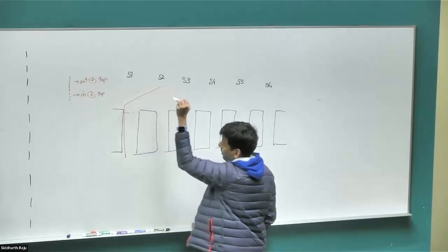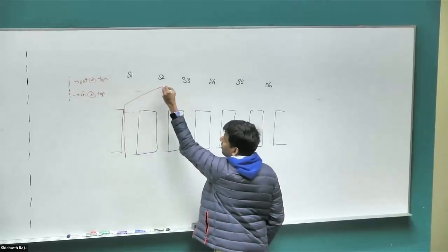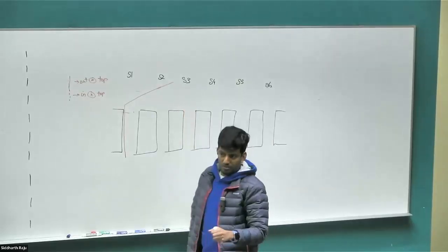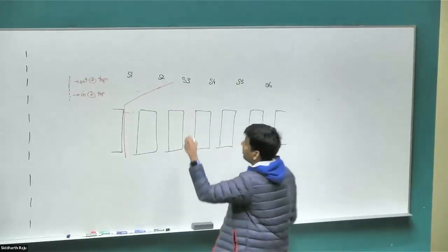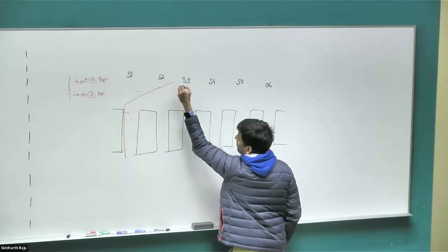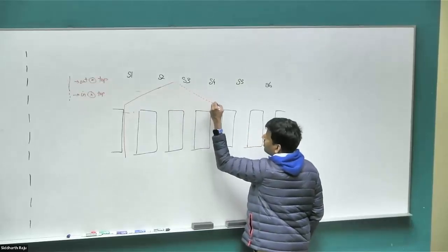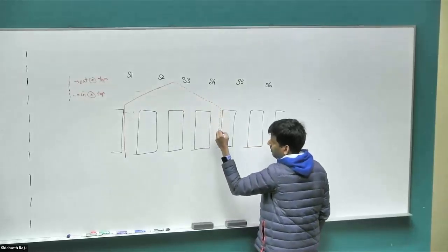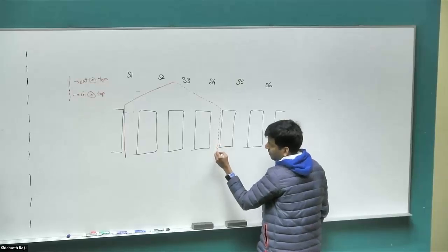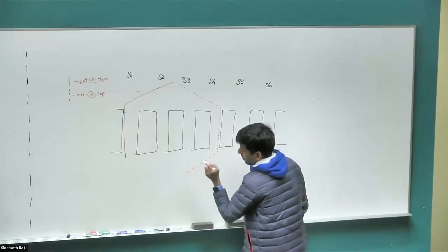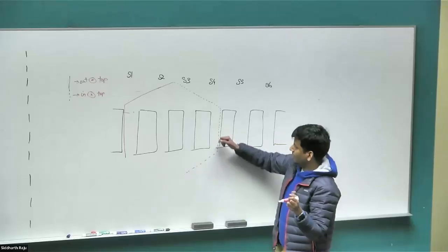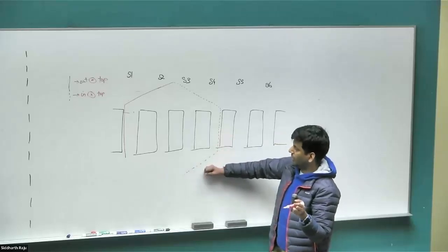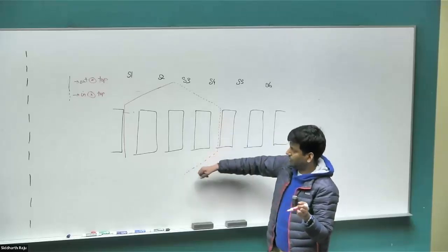And then where is the first conductor going? 4. Thank you. And according to my convention, I'm going to use a dot when it goes into the slot. Right? Okay. Where is this conductor now going, the one coming into slot 4? Where is it going to go next?